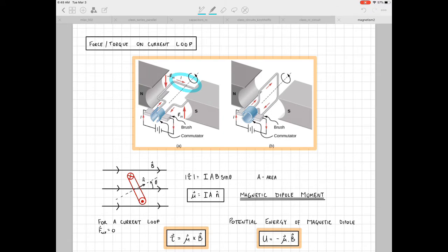That magnetic force would be in this direction. Let's see if we can draw it into the middle of the loop. But then you've got this portion over here that has a force towards the middle of the loop. And so those two forces essentially cancel out and don't contribute anything to the rotation. It's the forces on these two ends of the loop that are generating the net torque that the loop experiences.